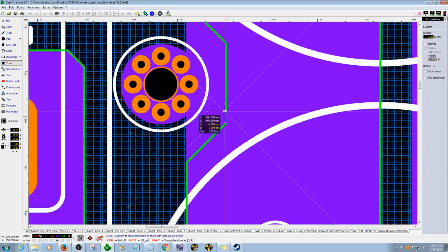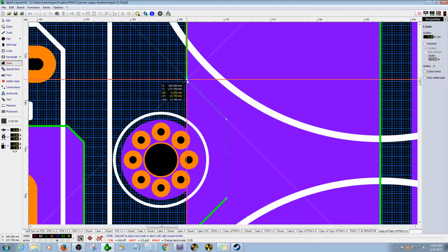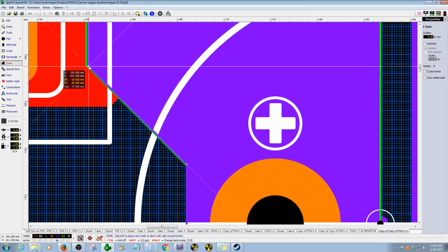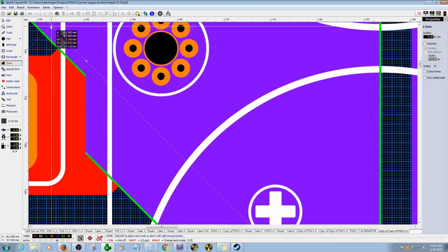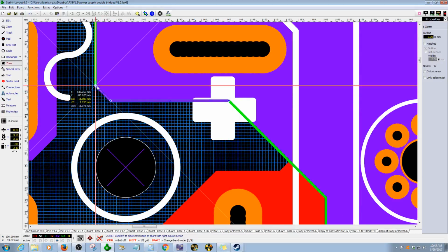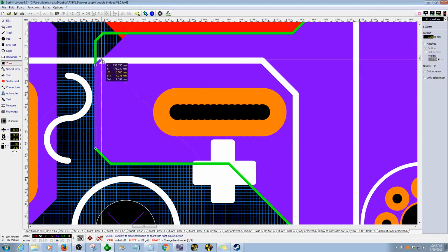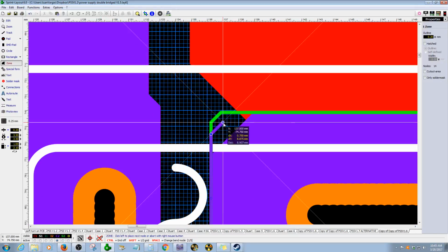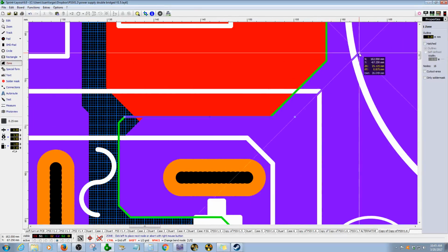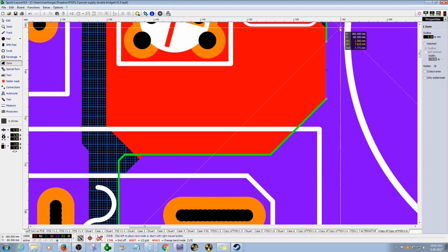Depending on the situation, if we need to eliminate some standoffs, we can do that too. We can eliminate the standoffs that are not really needed. But I think in some areas of the PCB standoffs are really needed, because we're gonna have 6 large capacitors. I'm not sure, they are pretty heavy. I don't know how much they weigh.